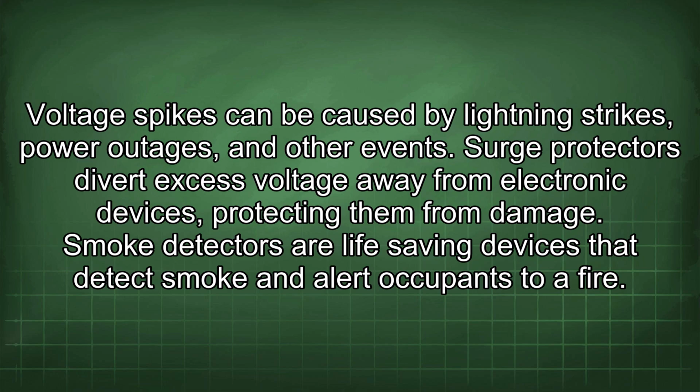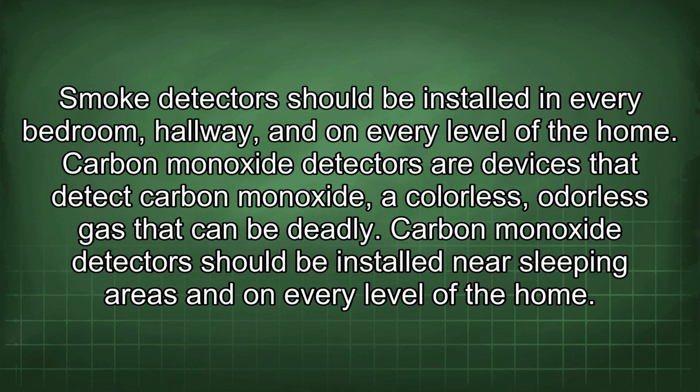Smoke detectors are life-saving devices that detect smoke and alert occupants to a fire. Smoke detectors should be installed in every bedroom, hallway, and on every level of the home. Carbon monoxide detectors are devices that detect carbon monoxide, a colorless, odorless gas that can be deadly. Carbon monoxide detectors should be installed near sleeping areas and on every level of the home.